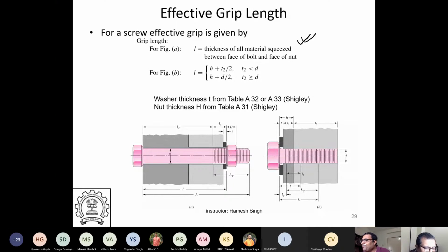And L typically is, and then there can be two ways, right? One can be a bolt, the other can be a threaded portion. So you have a thread and you tighten the material in the thread. In both cases, there are different L's. Here it is easy to compute L because L will be L_D plus L_T. The threaded portion is L_T, the unthreaded portion is L_D, so the sum of these will be the total length L. And all this you can find in Shigley, pages 832, 833, where washer thicknesses are known.